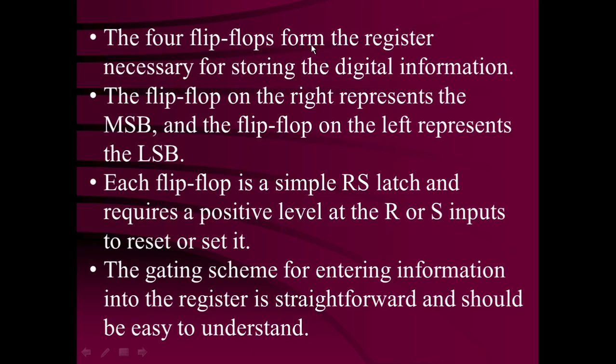The 4 flip-flops form the register necessary for storing the digital information. The flip-flop on the right represents the MSB and the flip-flop on the left represents the LSB, corresponding to the requirement of the binary ladder network. MSB is going to be on the right and LSB on the left of this binary ladder network, and accordingly the digital input data should be provided.